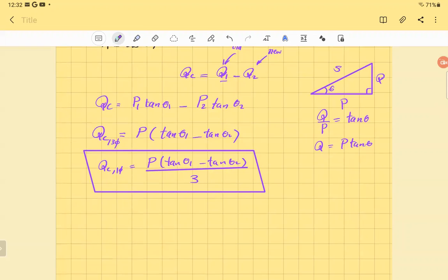Okay. Once you get the value of the reactive power required from each capacitor, it's an easy task to find the value of the capacitor. Why? Because we know there is a relationship between reactive power and the element itself, either capacitor or inductor. I'll refresh your memory. Q is equal to V squared over X in general, XL, XC, or I squared X. I'm talking about single phase. What about 3-phase? You will just have 3 times this one.